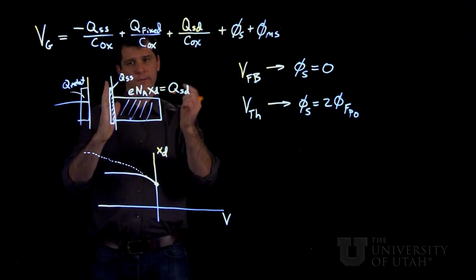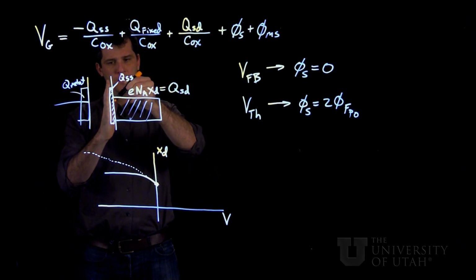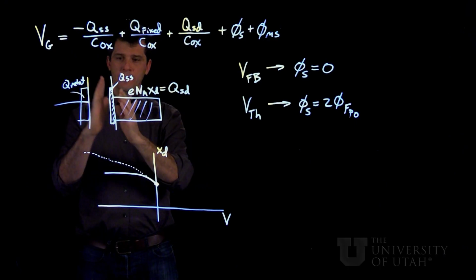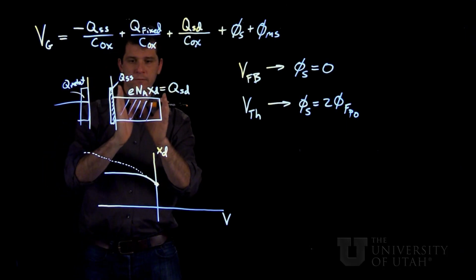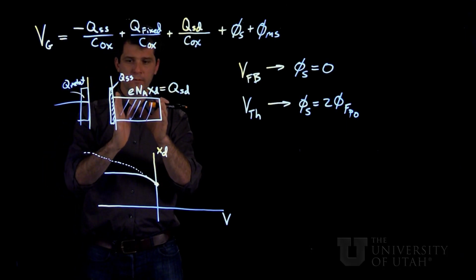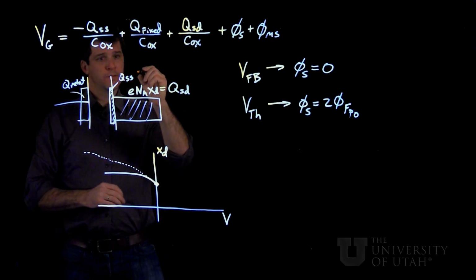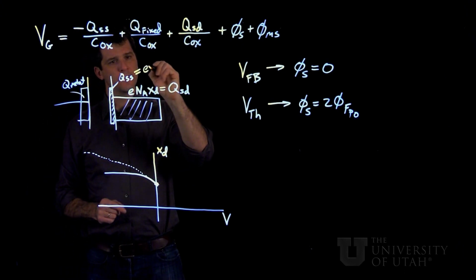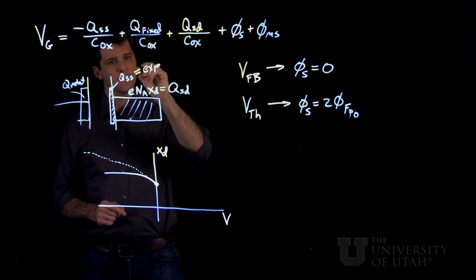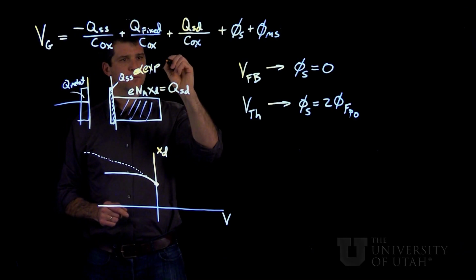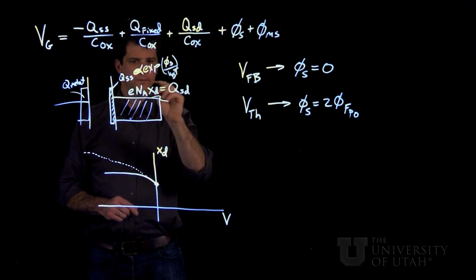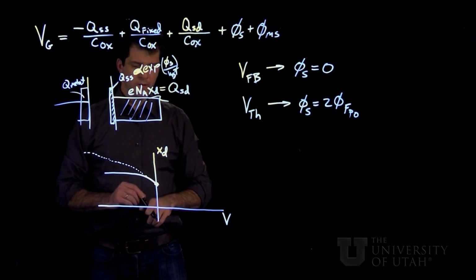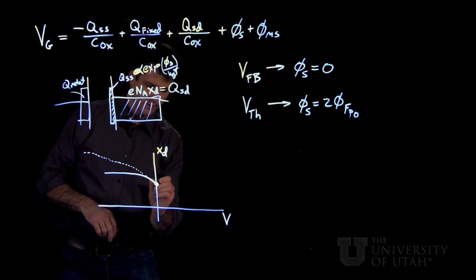And the reason is that as you start piling up those electrons, they satisfy the charge neutrality with the electrons in the metal instead of having to have that charge balanced by the depletion width. And as we saw, this Q_ss is proportional to the exponential of the surface voltage, whereas this here is only square root on surface voltage, and so the exponential quickly dominates.